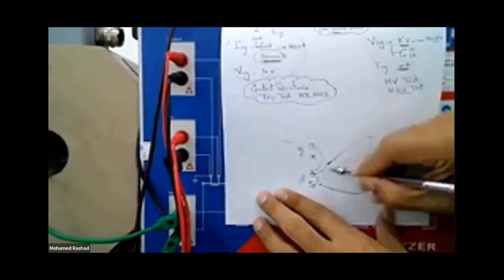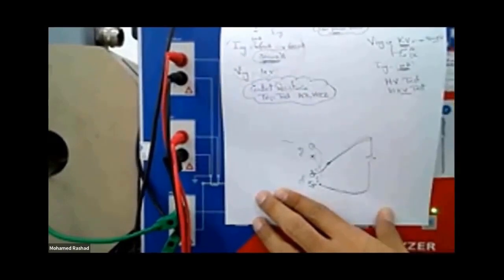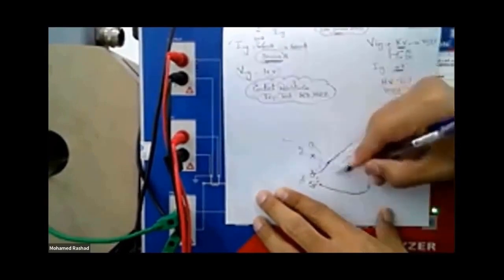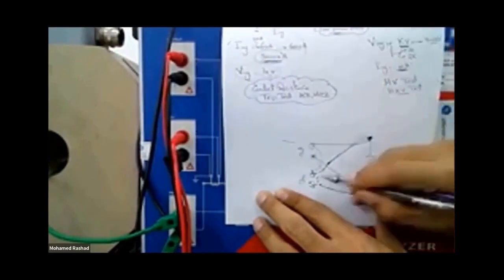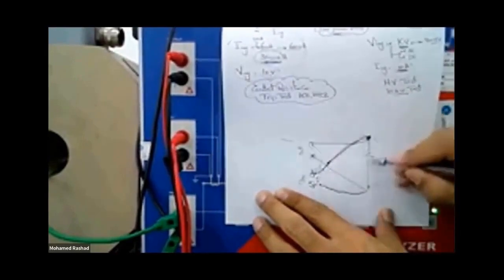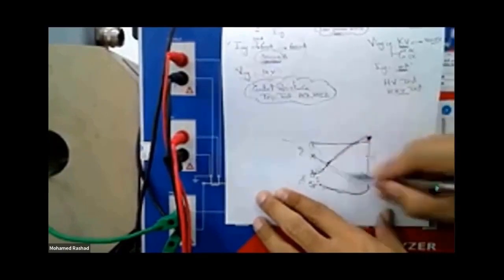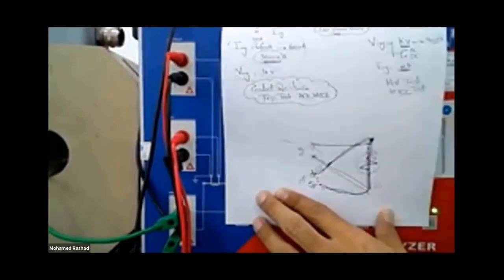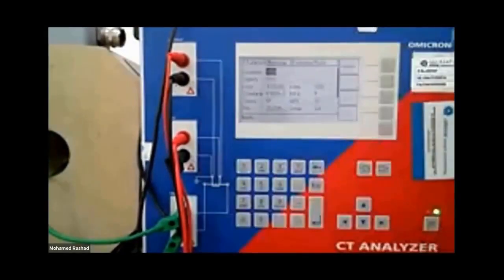And when you measure the voltage between these two ends, it means you are measuring the voltage across this entire resistance, including the resistance of the two wires of your test. Is that right, or am I wrong? You told me it's right, but that's not correct. I only want this resistance. So if I connect this here and this here, then now the current flows, stops at these wires, loops here, goes like this, and returns like this. But when I measure the voltage difference, I measure it only across this resistance. What is this resistance? This resistance only. So what is the correct choice for me? All right, that's one thing. The second thing is, as a steady resistance, the other thing is that my equation, the equation specific to my circuit, is the one we talked about.